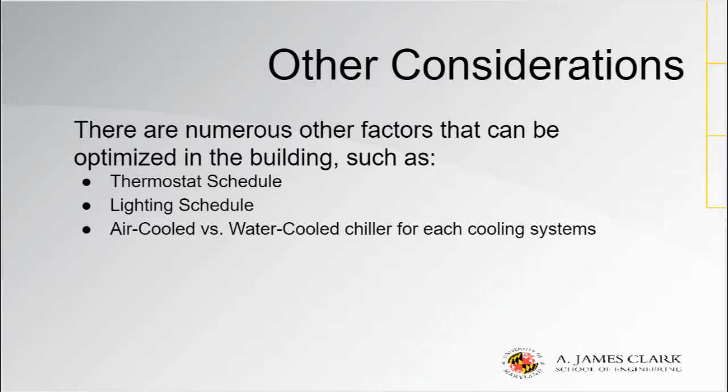So there are plenty of other considerations that we had to take into account when doing our energy modeling through OpenStudio. Basically, we had to take into account things such as the thermostat schedule, the lighting schedule, and whether the data center cooling method should be air-cooled versus water-cooled. Though we can't go over all of them right now during our presentation, our BCA will cover basically the rest of all of the modifications that we've made for our energy model.